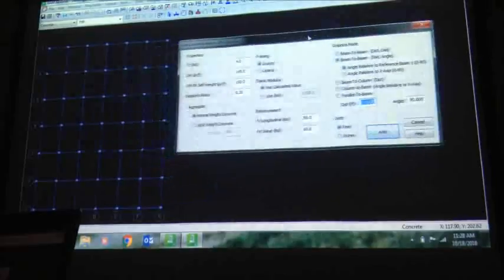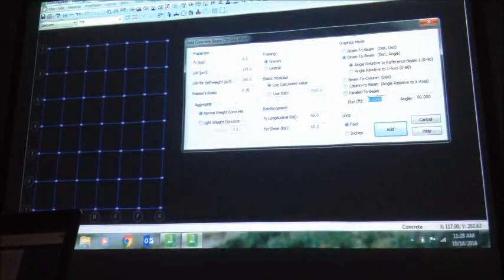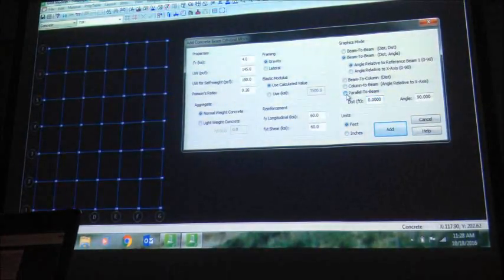Okay, once you have that, now I want to do a little bit trick, not a trick. Remember I said that I will make this layer, this row with multiple beams, so that I have actually a one-way slab. Okay, so what I will do is, I will place one beam here and one beam here. Right? So if I say go beam, add off grid, that's one way of doing. Add off grid, it will come up with like that.